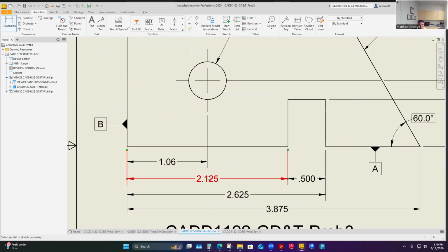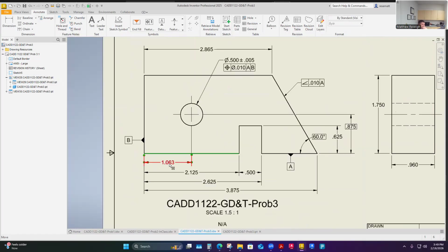Okay, I will copy these properties and apply them there. And this is the other one, and I'll pull my center line to meet my extension line. This one is going to become basic as well. I think that's a copyable property here. Let's just see, copy properties and add it here. All right, so those are my theoretically exact locations for that hole.